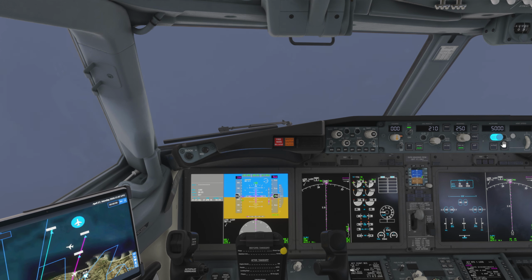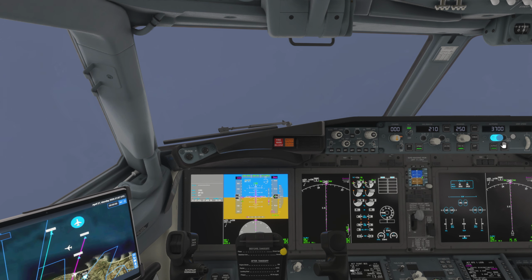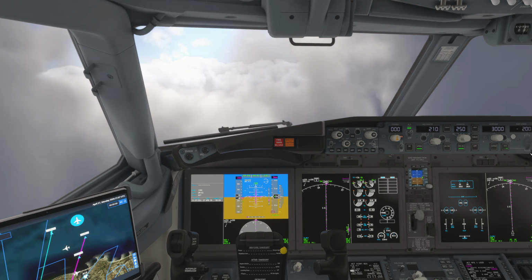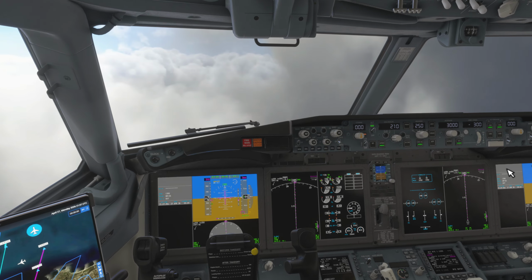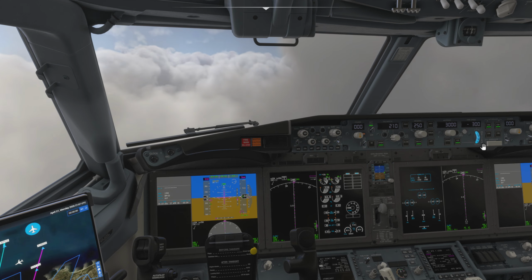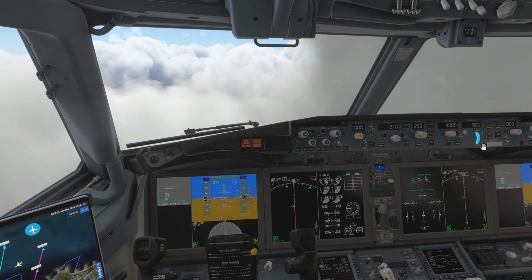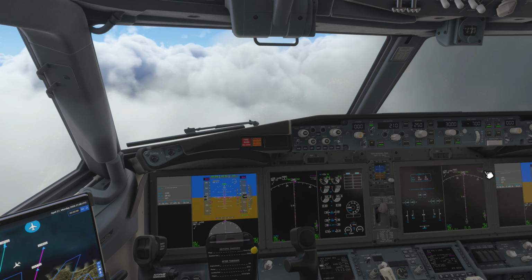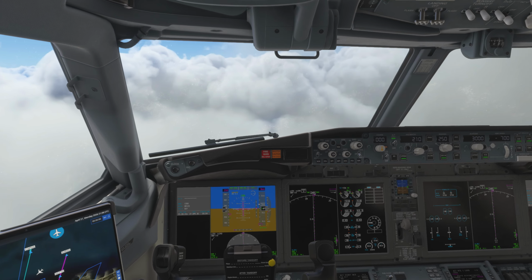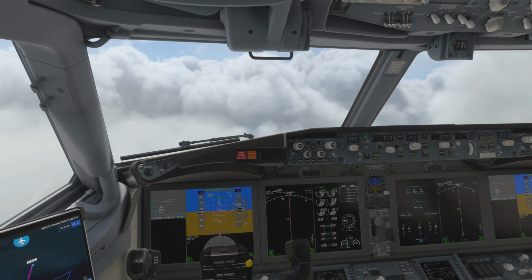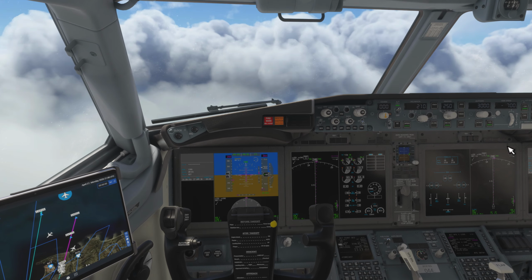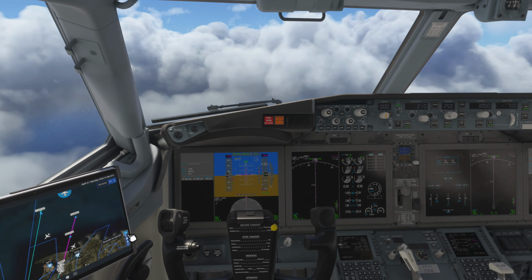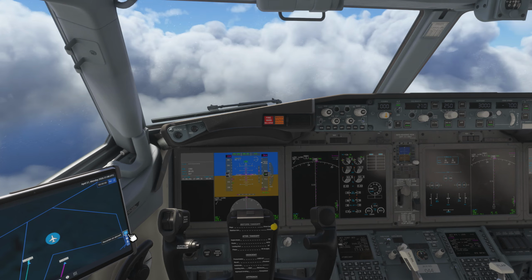So let's start lowering our altitude here. Let's take it down to 3. And we'll get the vertical speed, just this wheel right here. Activate your vertical speed, which is the speed at which the aircraft will descend. Put her at -700. She's descending at 700 feet per minute with that, okay? And let's center this on our EFB so we can see better.